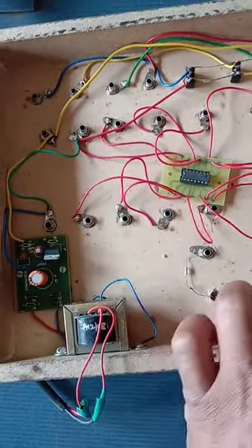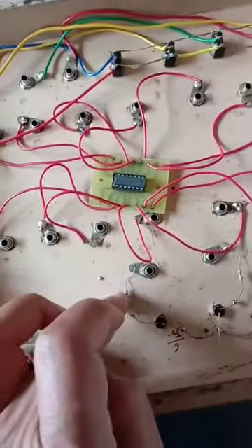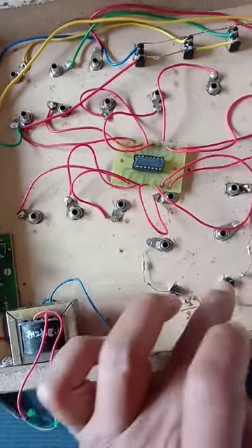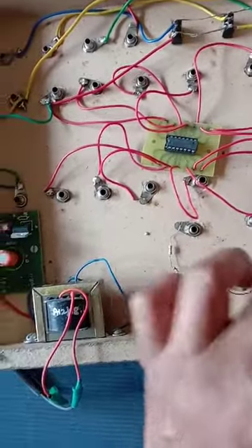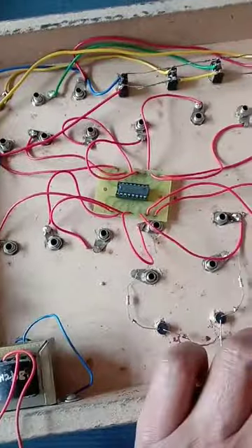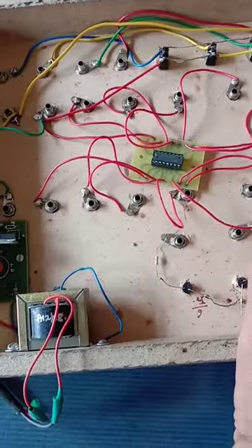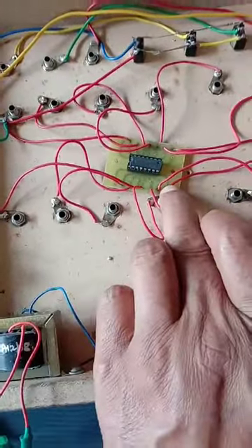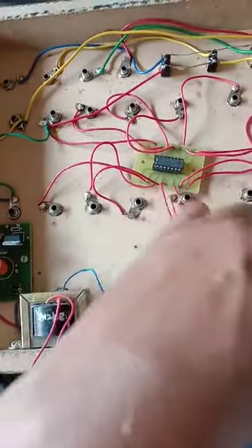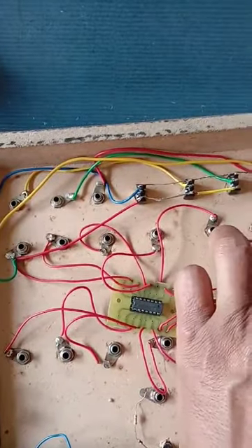These are the LEDs, and these are the series resistors, 330 ohm. These resistors are connected in series with LED. The LEDs are connected here, and cathode of each LED is shorted and connected to the ground. Ground means pin number 7. See here, this is pin number 7 and it is connected to ground. So all these cathodes of LEDs are connected to ground pins. These are two-way switches, or one pole two-way switches.